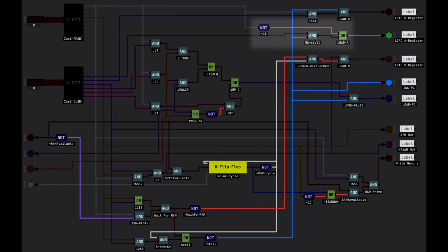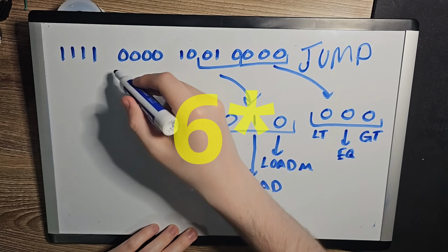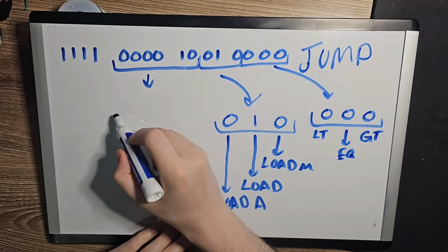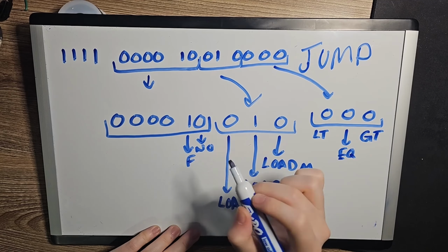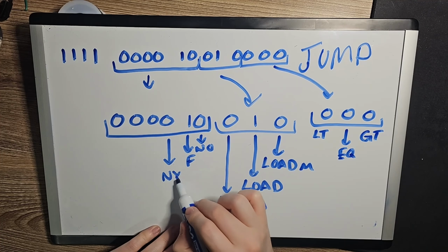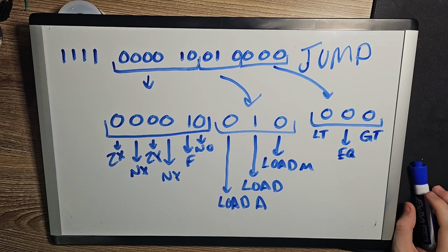So we have an OR gate that checks whether or not bit 15 is on and whether the load A pin is on the C instruction. Now the names for the next 16 bits may look familiar. That is for our ALU operations. We actually don't let the control logic alter any of these pins. They just go directly to the ALU because there's no need to change them.